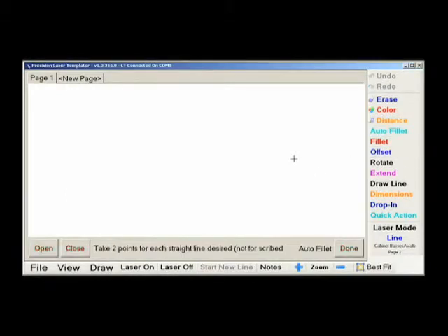Autofill is used while templating. The way it works is the first two measurements taken will create the first wall, cabinet base, or surface. The next two measurements taken will create the second. After the second surface is created, a corner will be filled in between those two. This avoids the need to click Start a new line between every line, but can only be used on straight surfaces. This is not to be used for scribed walls, but can be used in conjunction with scribed walls.